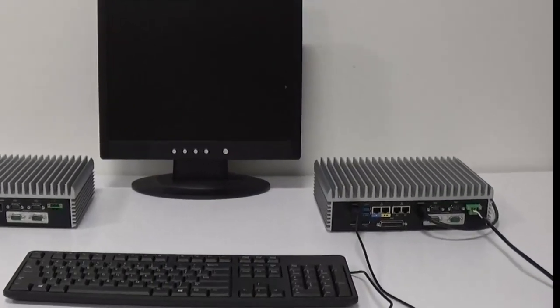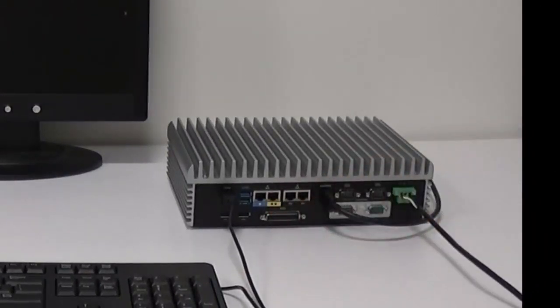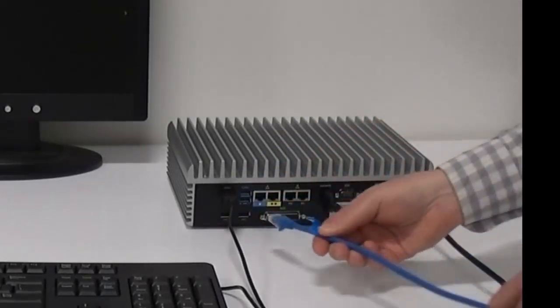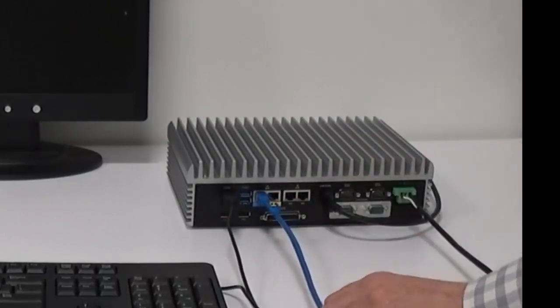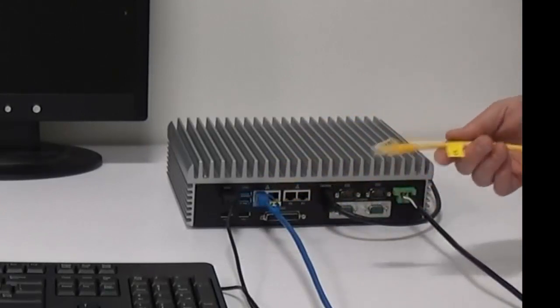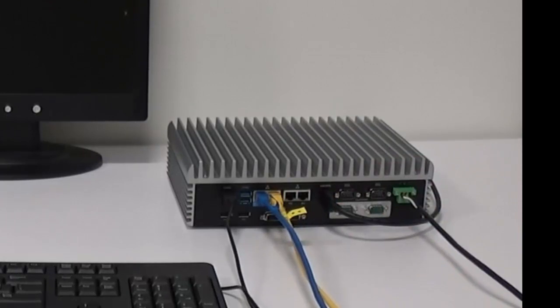We'll first connect the cables to the first node. Notice the ports on the ztC Edge node are clearly labeled. The private network port is blue in color and has a single white dot. The A-Link port is yellow in color and identified with 2 black dots. The corresponding blue cable that was shipped with the nodes also has a single white dot. Connect the blue cable. The corresponding yellow cable that was shipped with the nodes has 2 black dots. Connect the yellow cable. There are also two additional network ports, P1 and P2.